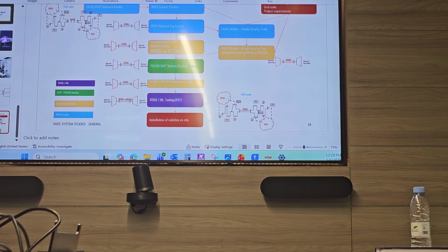For example, for the load flow, generally you have heard of the n-1 requirement, or n-2 in some cases. So you also will simulate this. What if a line is out of service, for example for maintenance of one line, and one generator trips because of something?